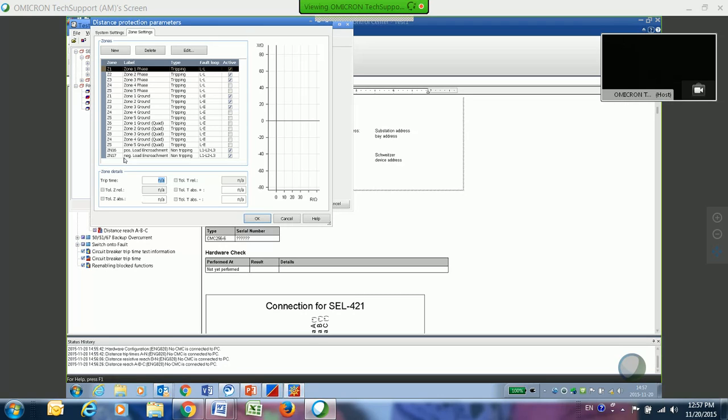But, being an international company, we want to make sure that we try and incorporate as much information as we can into these different test plans. Based upon your settings, these would be parsed out. I may not have 5 or 6 or 7 different types of areas that I'm looking at. Here we've got Mho circles and quads, and we've also got load encroachment coming in. This brings a lot of different information into my test plan, and based upon what my settings are, you may or may not use all that list of things.